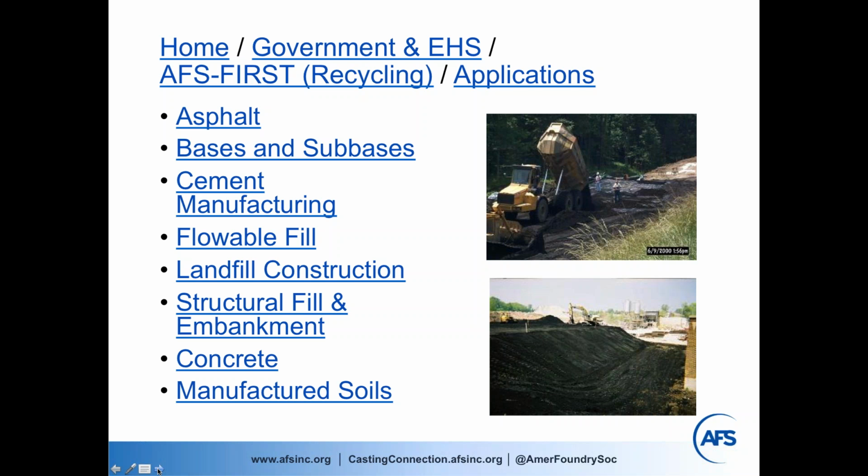So while that may have been the only option for some foundries in the past, today, as the state regulations are becoming more realistic, many foundries may find that working with local contractors for road base or for blended aggregate road bases or for sub-bases, structural fills, and embankments may in fact make a whole lot more sense than trying to ship your material out of state to a cement kiln.